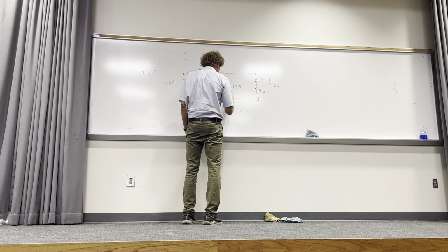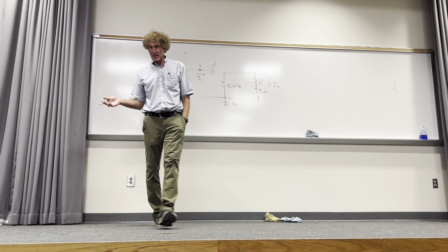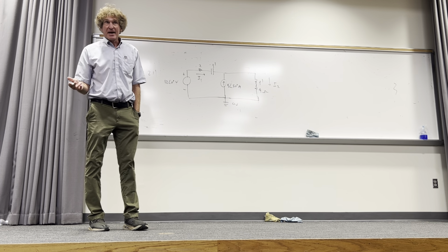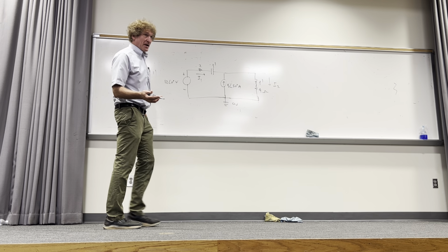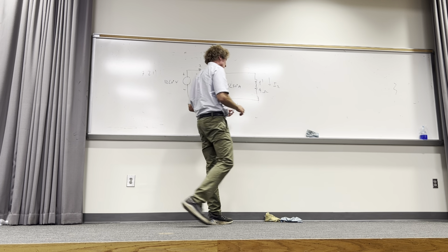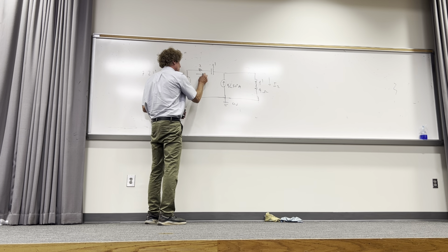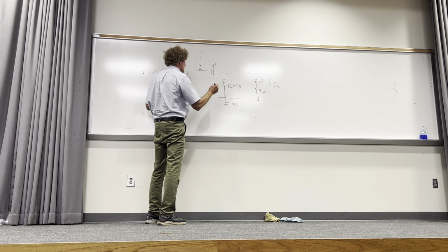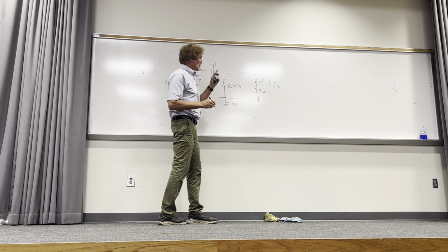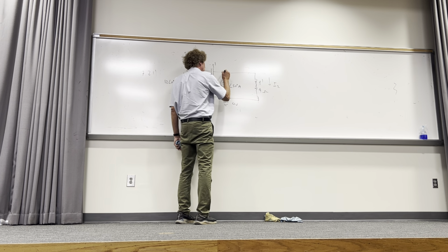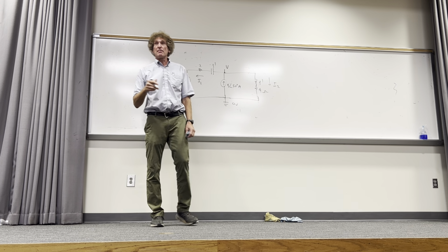So if I go down here and ground that, we're 0 volts. Now I'm going to do nodal. If somebody has a strong preference for something else besides nodal, we'll do it, but I'm using nodal. And I'm going to do one other thing too. I'm going to redirect this current this way, you'll see why. I'll call that I1, and I'll call that I2, and this will be my unknown potential. I'll just call that V. Do you all agree with that?